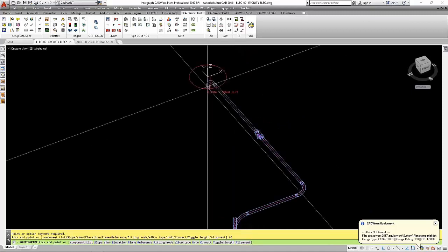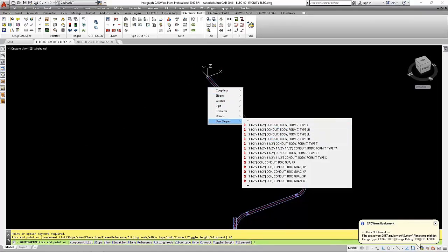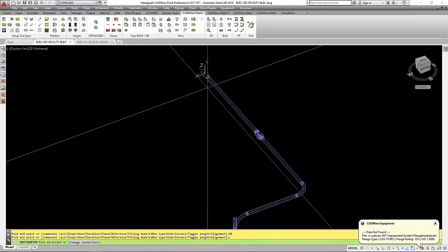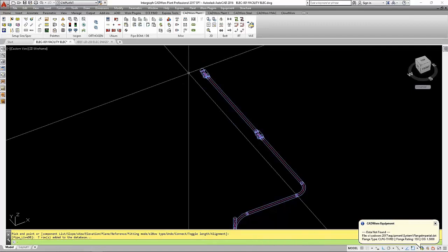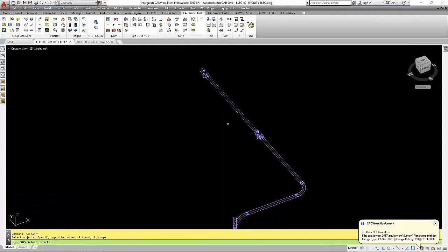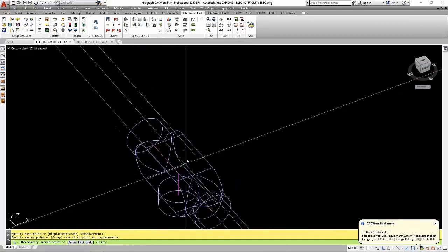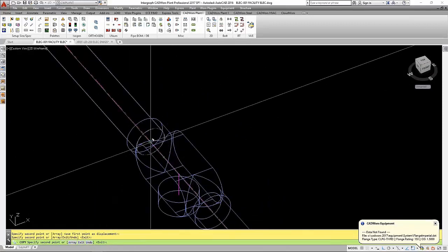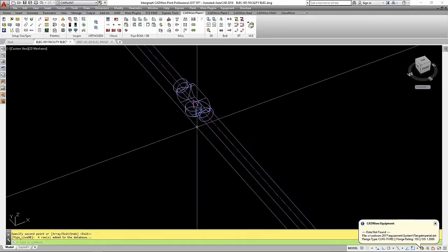I can just continue on. So CADWorx is just real-time routing. Go to my user shapes, and we're using the user shape capability. There's another T. Drop a T in, pick the direction. There are 2 T's. Let me do some copying. So now that I've got one in there, I could keep drawing, but it's CADWorx, so I can copy and copy and copy. This is one of the wonderful aspects of CADWorx, its ease of use in those terms.